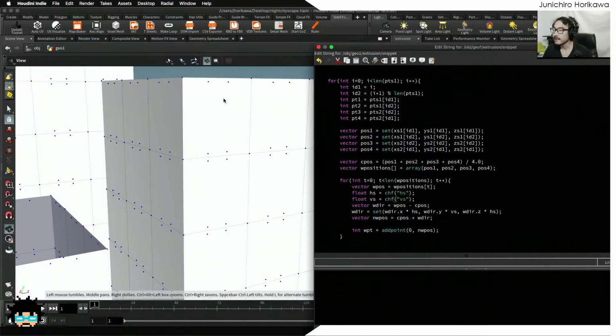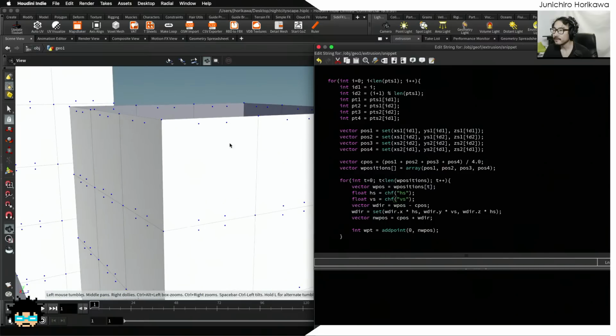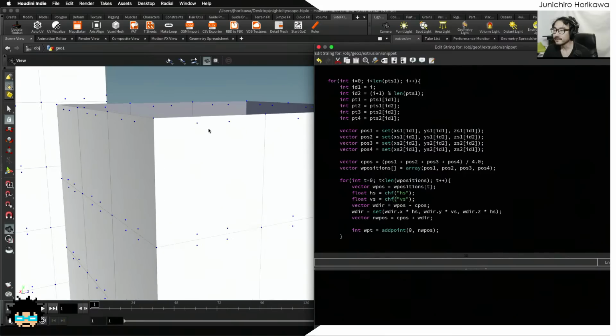Okay, now the next thing I need to do is to open up or create edges so that I can change the color of this window. To do that I need to create 4 side faces using this point, this point, this point, and this point for each side. So in total we need 4 frames as polygons for the window.